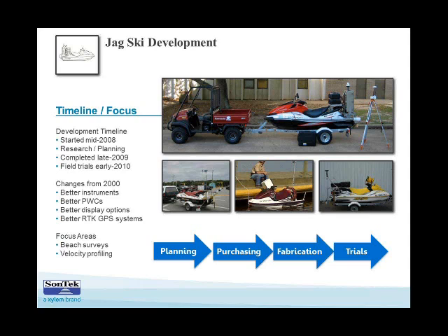It's a 5-point depth sounding device, so it's an ADCP, but it also is a depth sounder and gives 5 different points. It profiles the water velocity, and it's a solution that has integrated GPS, but can also switch to bottom tracking. So if you lose GPS, you're not out of luck with your boat track. It can switch to bottom track and then back to GPS if you get GPS again.